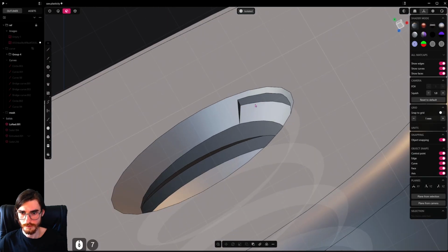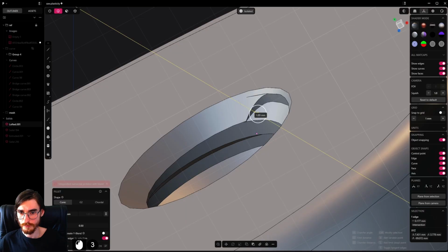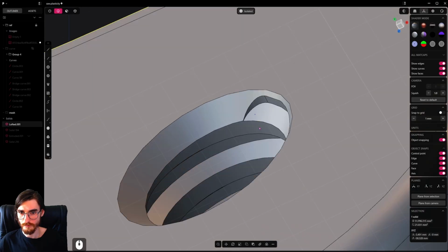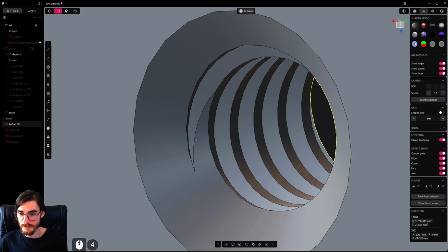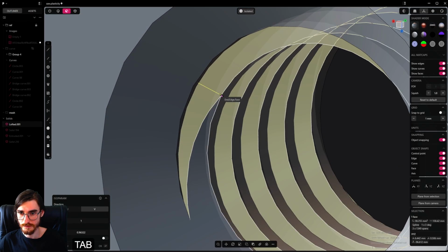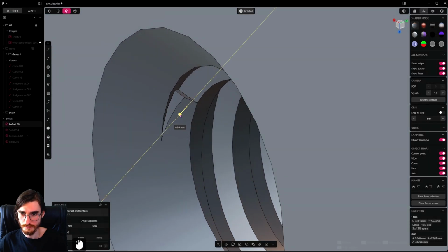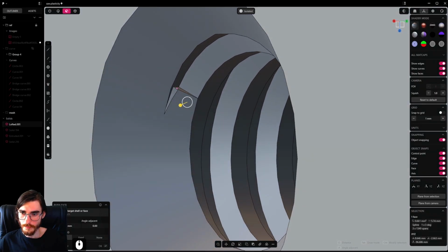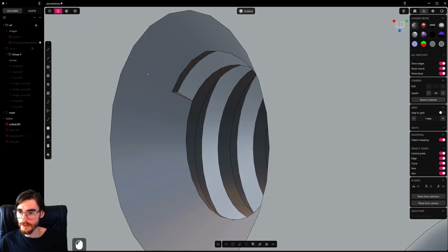Like this. Good. And if you really wish, you can drop a bevel over here, just to make it juicier. Or you can leave it like that, it doesn't matter at all. These things, if you're doing it for a game or something, will be deleted. No one will see them, definitely. Okay, like this, and select this part, F, match face, just will make less pain.